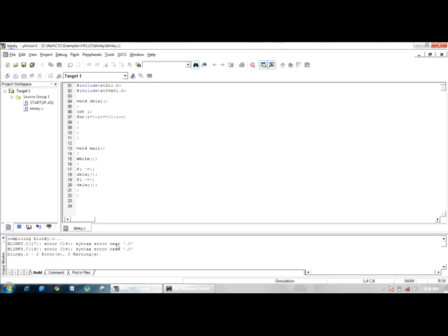Syntax error near point 0. So maybe this point 0 is not compatible. Many compilers support this point 0, that is definition of the pin number with a point. So let us give it as _0. So this is all trial and error. So port 1 _0 indicates port 1 pin 0. Click save again and compile.